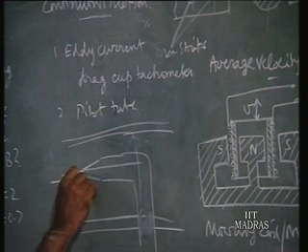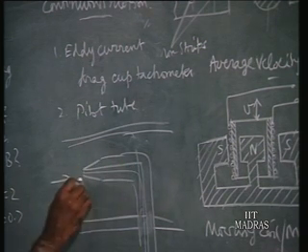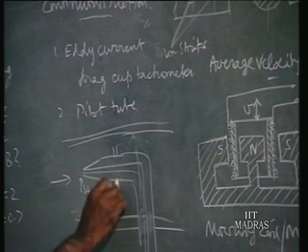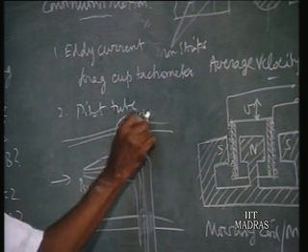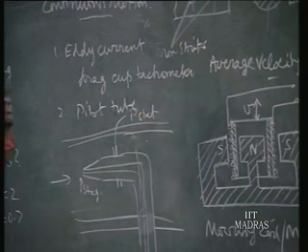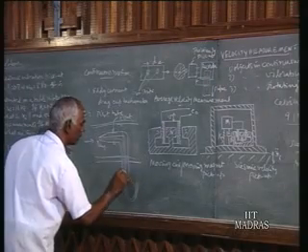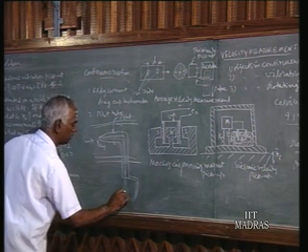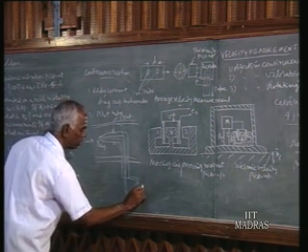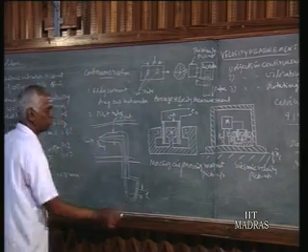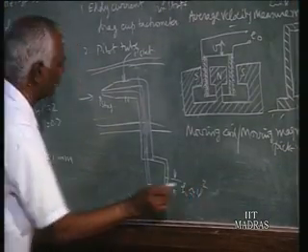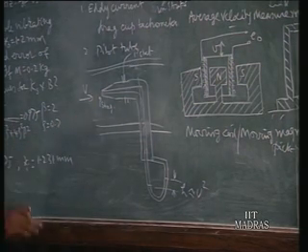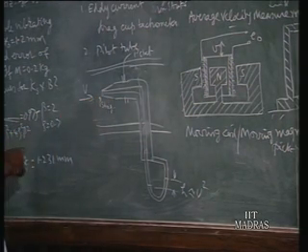This is the pitot tube. You take this, this is your P stagnant pressure, and we have got the static pressure. This is P static. They are connected to a manometer tube, and the difference between the columns in the manometer, say height, is proportional to V square. V is the velocity of the fluid. This is the pitot tube principle, which we will learn in detail in flow measurement.